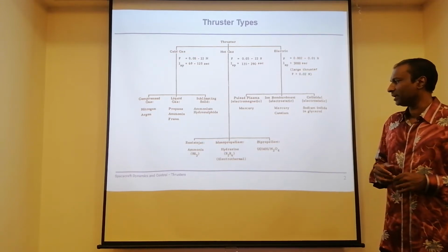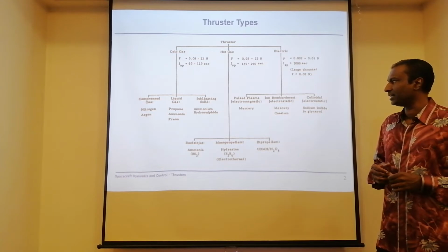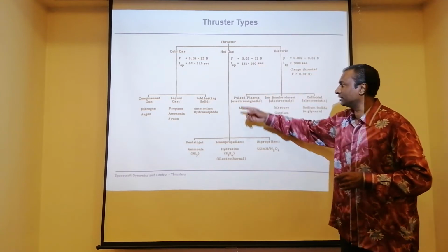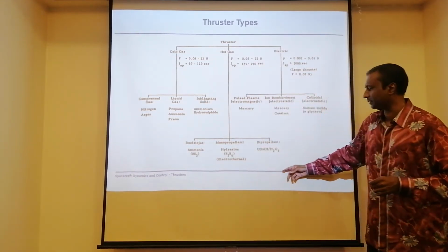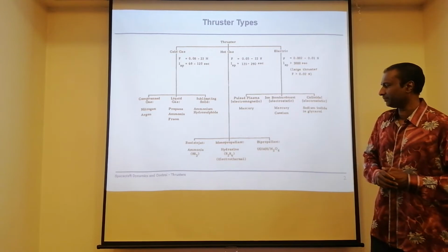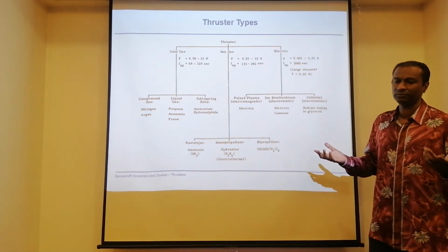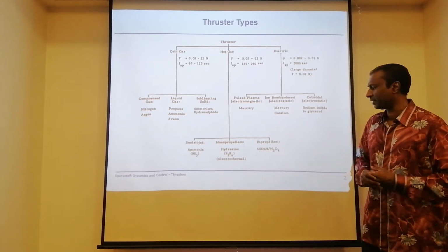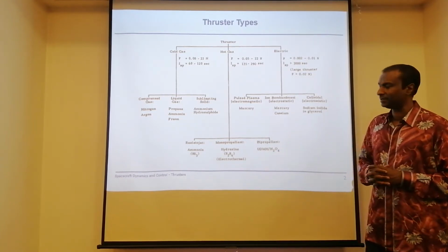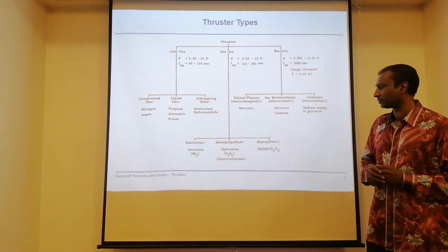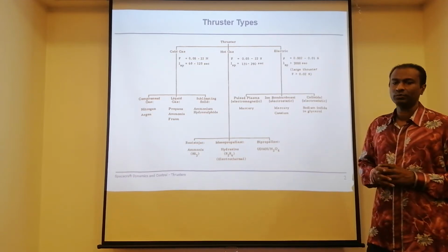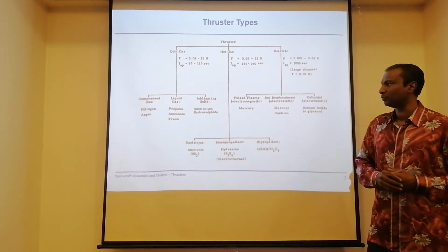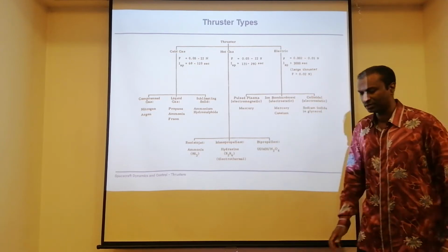If you see the options that we have, for example, hot gas is a quite typical example. You have, for example, bipropellant. You have the oxidizer. You will have the fuel, here unsymmetric dimethylhydrazine, and N2O4 nitrogen tetroxide as the actual oxidizer. So these are quite typical. I think you have been exposed to them. So there are many options for how the system is going to look.